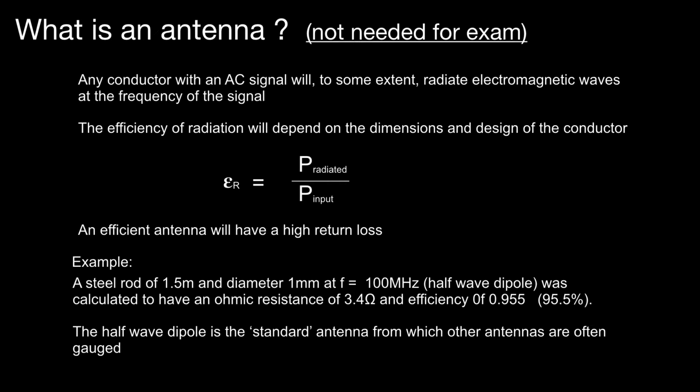But sometimes you'll see a yagi, for example, might be quoted as having a gain of 6 dBd, or that would be 8.17 dBi. So there we go. Right, so the half-wave dipole, if you like, is the reference antenna which we keep going back to when we're gauging how things are doing.